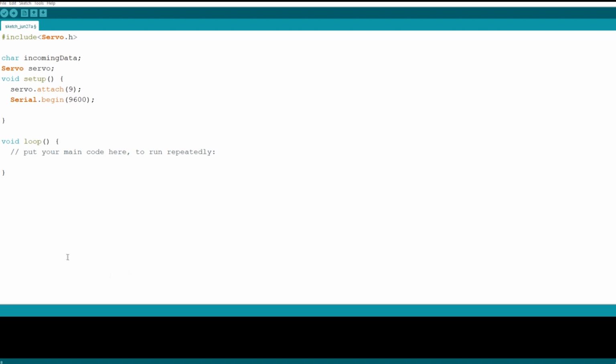And now let's set the starting angle of our servo motor. As you know, we need to set our arm to full open, therefore we need to set it to 180 degrees. And if you want to control our servo motor, let's call here first our servo object and put a dot, and let's call our write method. Also open and close parentheses and put a semicolon, and let's move inside of our parentheses and define the angle as 180.